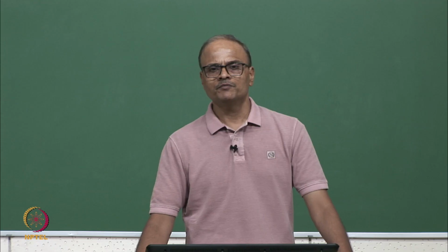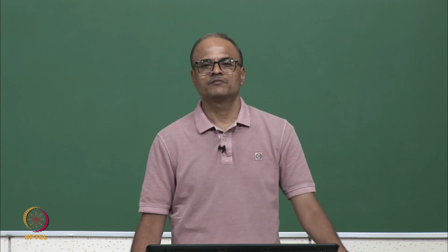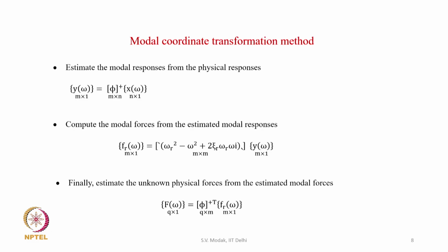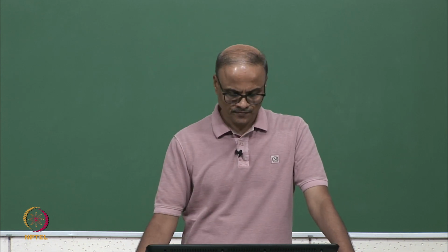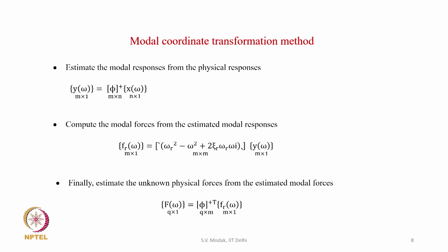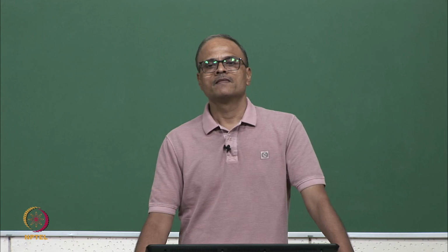One advantage of this method is that the pseudo inverse needs to be computed only once. The pseudo inverse of the mode shape matrix phi can be computed in advance, and then these 3 steps can be implemented at each frequency. The pseudo inverse remains the same at all the frequencies, and hence its computation need not be repeated at all the frequencies. So, these are the 2 methods of force identification, the FRF-based method and the modal coordinate transformation method.